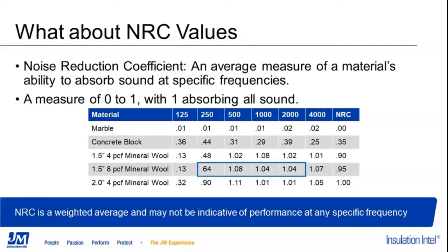And you'll see in a future slide in the NRC where you can actually get a noise reduction coefficient value greater than 1. And that is actually just due to limitations or shortcomings in the way the test procedure was defined and how the unit of absorption within the standard, or the definition of how you measure and calculate noise reduction coefficient, was originally established.